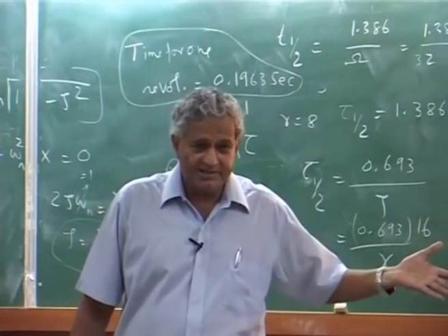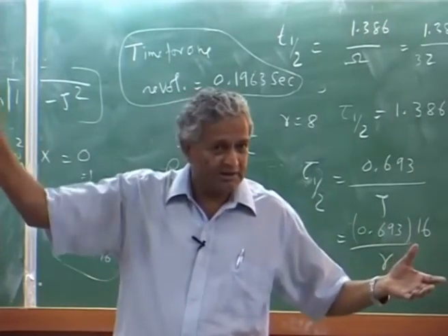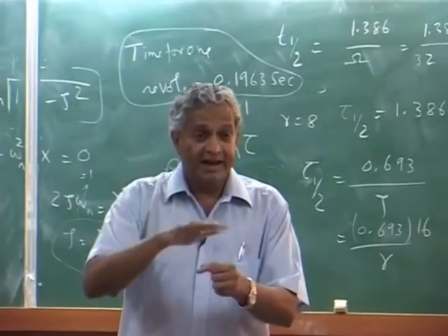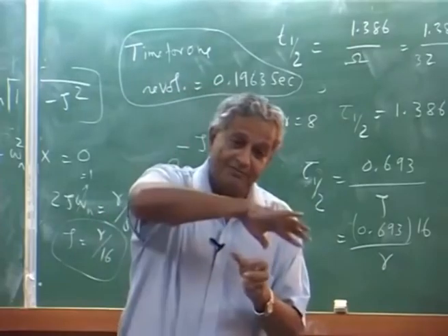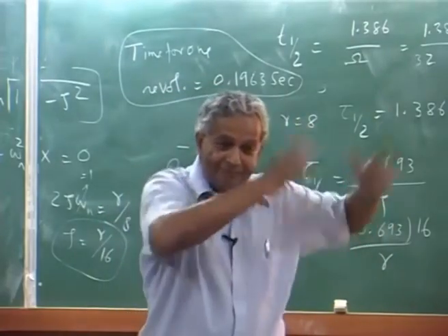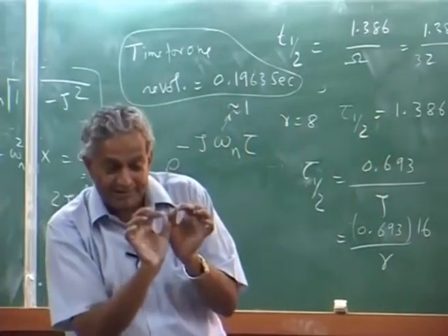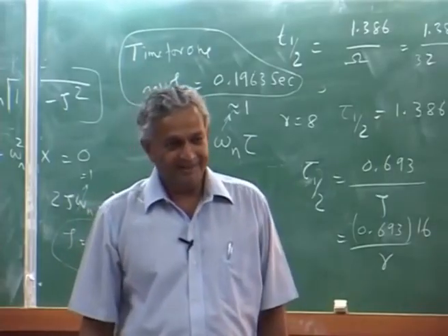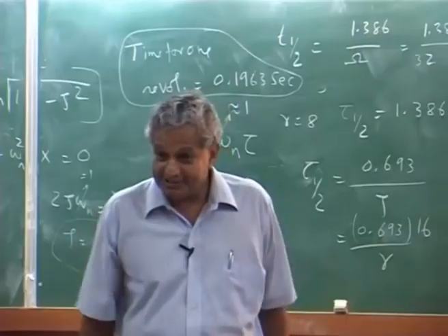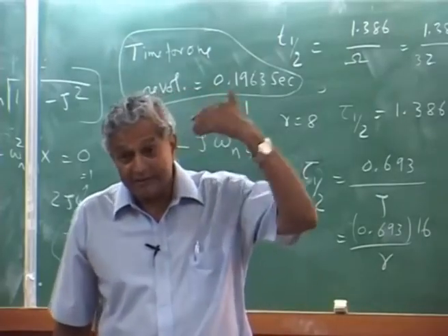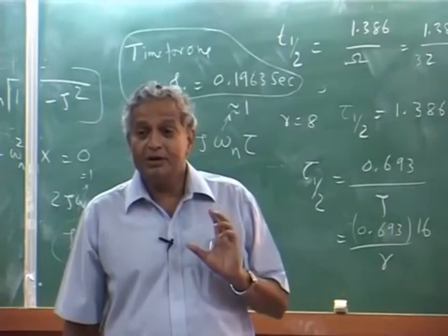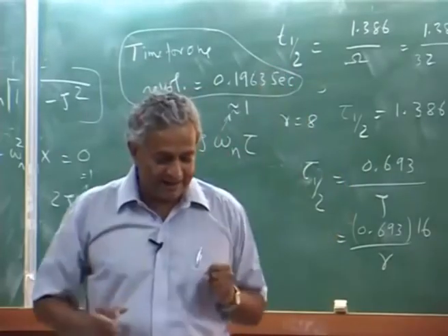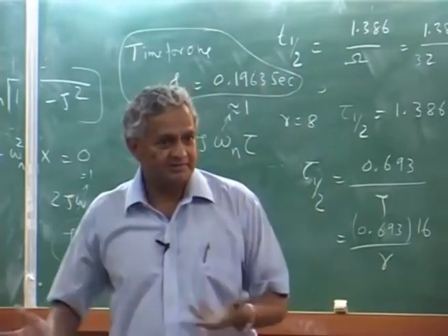The moment I look at the steady state value, the dynamics is gone. Give input, there is a change in force, that is all. How the change in force has happened is because of the dynamics of flap motion, the change happening over a time, but I neglect that. So, when I solve flight dynamics, they really neglect even the flap dynamics, in the sense they assume it is quasi static. Not that the flap dynamic equation is thrown off, but I say I give an input, and instantaneously I change my loads.